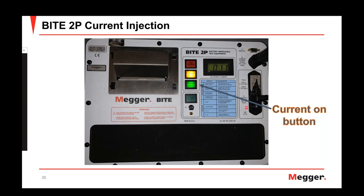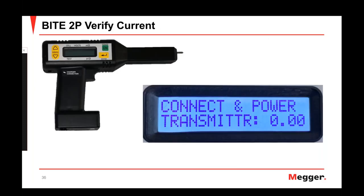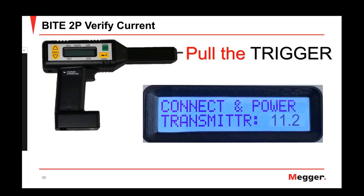The next step is to go back to our receiver and refer to the screen, and we're going to look for a current value. We can see here that we have 11.2 amps registering on the receiver unit, and the current transmitter says that we're outputting 11 amps. This is an acceptable reading, and we can go ahead, pull the trigger on the unit to record that value, and move on to taking our impedance measurements at this point.